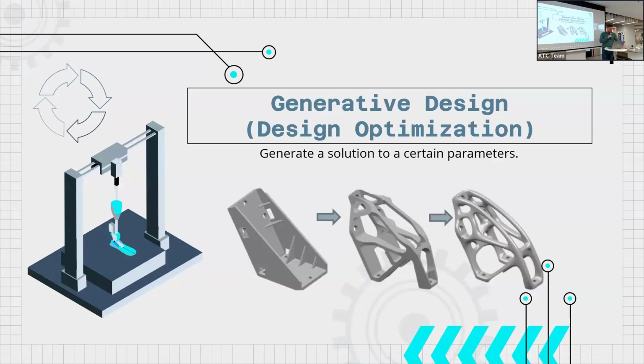By using generative design techniques, we can use AI to explore a really wide range of design possibilities, which are based on certain constraints and objectives, which will result in a super highly optimized structure that is lightweight and efficient. For all of you who have a printer at home or have used a 3D printer, you know how expensive that material is and that you want your part to be as lightweight as possible. So here we can see where we started with the initial joint, and then using generative technique, we've been able to scale it back to have the same strength as that first joint at 33% of the material cost.